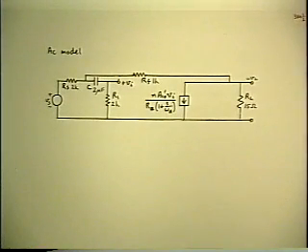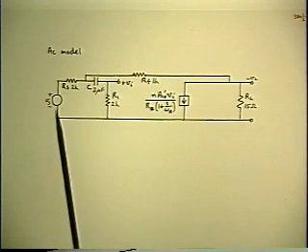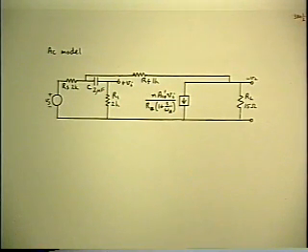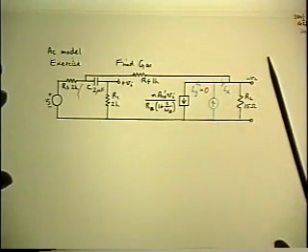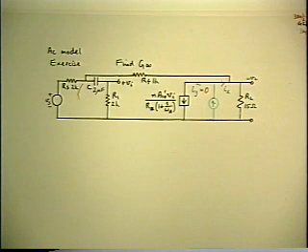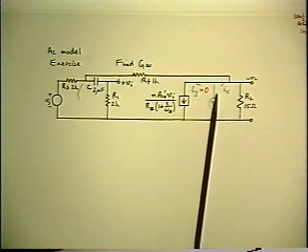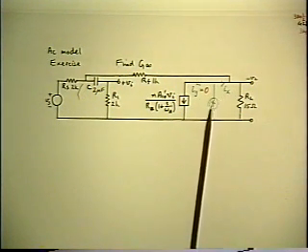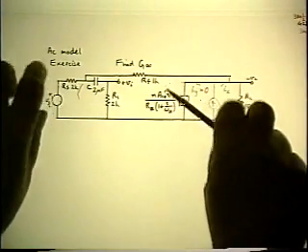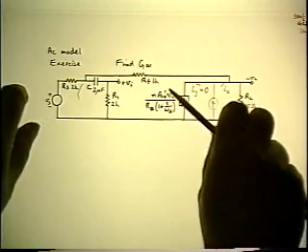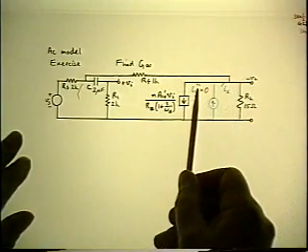And the procedure that we've established for finding g infinity is we can use the same model and the same injection point for a test signal, and we restore the original input voltage, and we use null double injection to determine the g infinity. So we've already chosen the injection point for the IZ. We restore the VS, and we twiddle the two knobs until we null the IY.